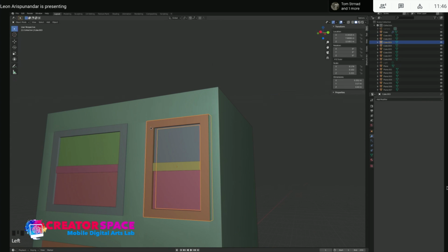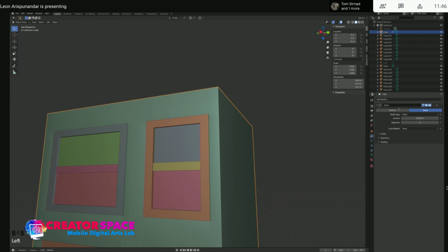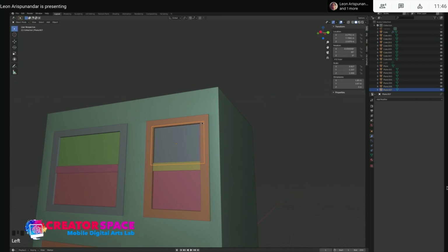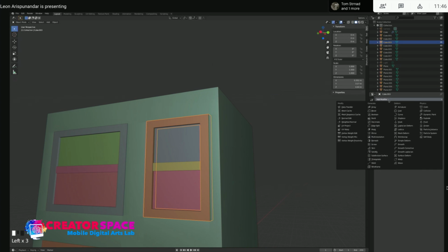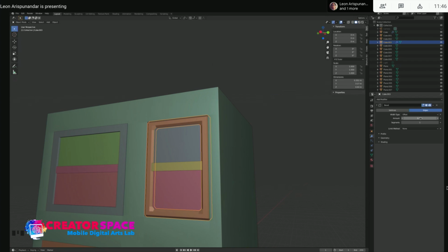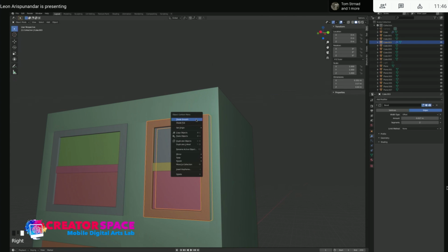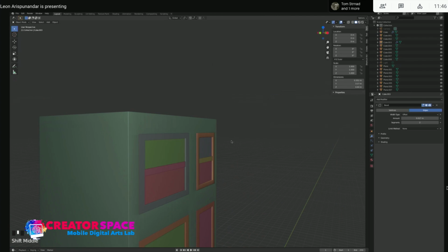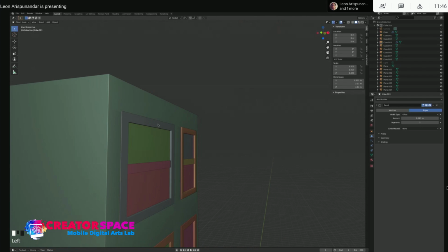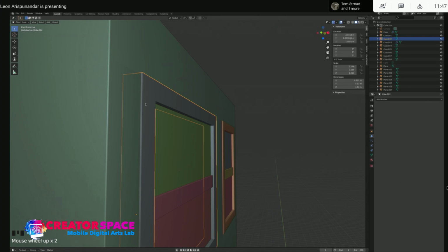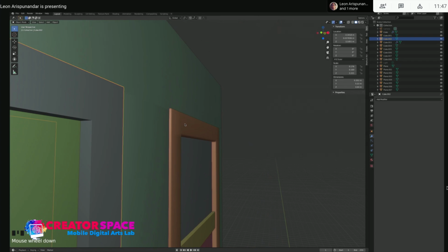And what I want to do is the same thing here. And then I'm going to add another bevel. This is a modifier. You can find it here. Add bevel. Too much, so we want to bring it down closer. That's more segments. And then shade smooth. You can see it looks much better instead of a sharp angle. You can see in here it's got more curve.